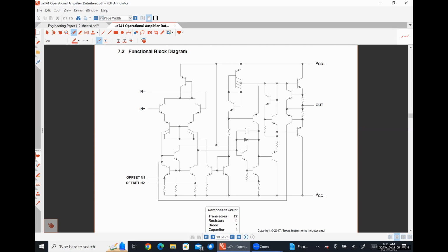The op amps that we're going to use in the lab Friday actually don't contain offset terminals at all, and there's actually 2 op amps on the chip. But there's a lot of different configurations and stuff like that. So in order to understand where you would connect things practically using an op amp, you need to have a copy of a data sheet with a pin diagram that tells you where things are, because they are not remotely consistent between various models. Okay, so, all right.